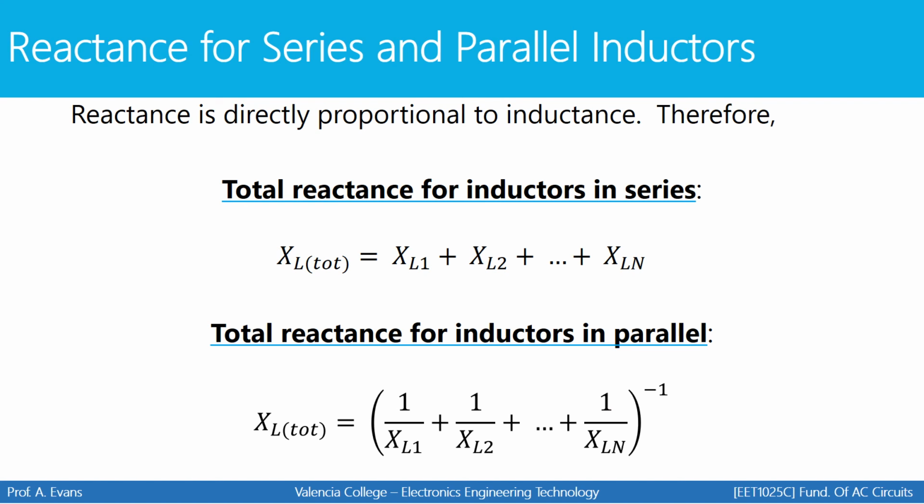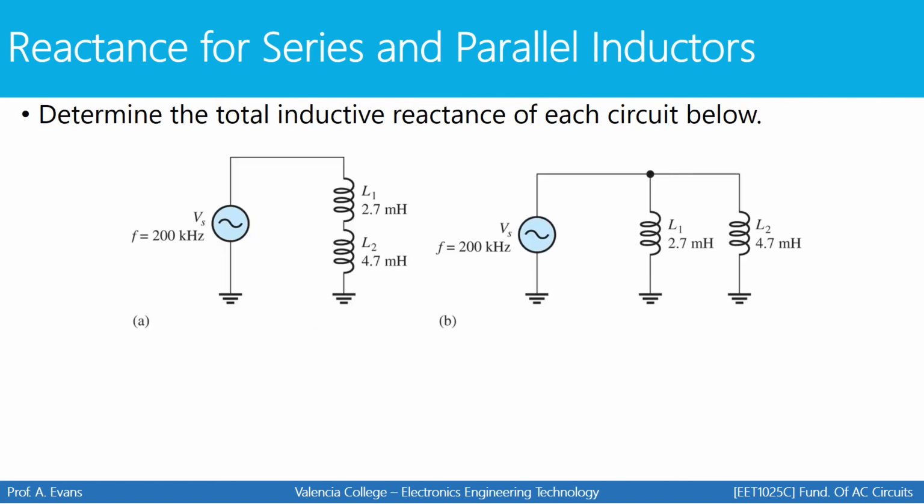So just like with capacitive reactance, you can combine inductive reactance the same way. Inductive reactances in series will be added together. Inductive reactances in parallel will be combined the same way we combine parallel resistors.